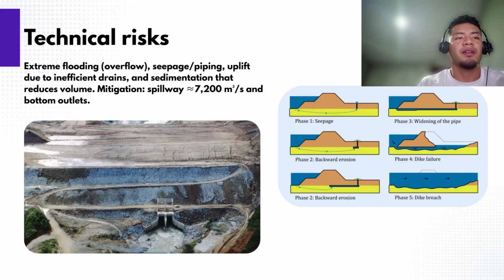Technical risks. San Carlos is not a failure case. Typical risks in earthfill dams include reservoir over-elevation from extreme rain, seepage and piping due to high gradients, uplift if drains fail, and sedimentation that reduces useful storage and changes hydrostatics. The spillway capacity and the bottom outlet are the key mitigation barriers.